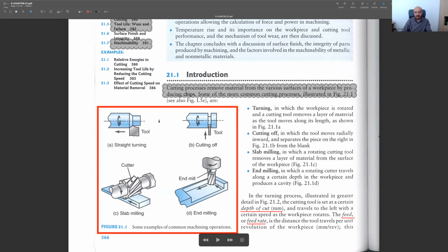And this is another important issue in machining. We need to have a relative motion. The tool and the workpiece both cannot be stationary. If that's the case, then we cannot talk about machining. One of them should be moving, rotating, and the other one might be stationary, or it may be just moving. And in this turning case, as you see, we'll discuss the details in the next chapters, but right now we can say that since it's a turning operation, the workpiece should be turning at very high speeds, and the tool is being fed this time from right to left.